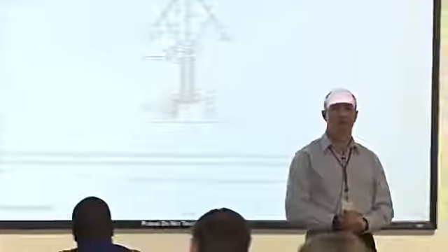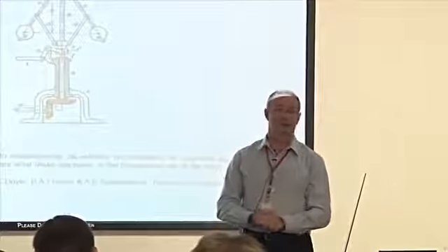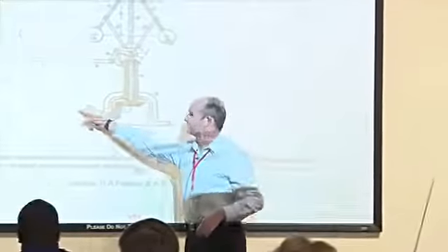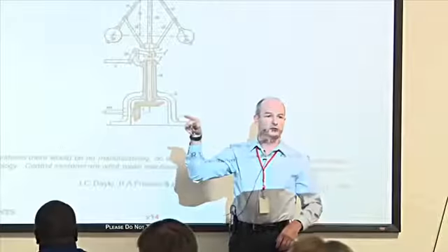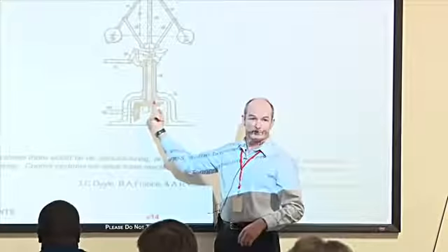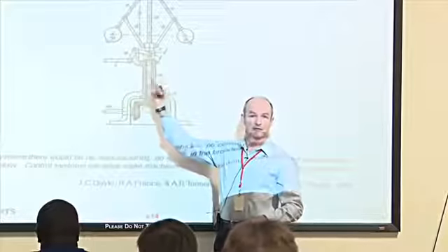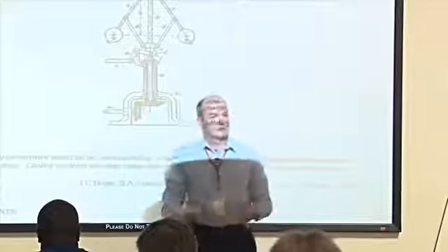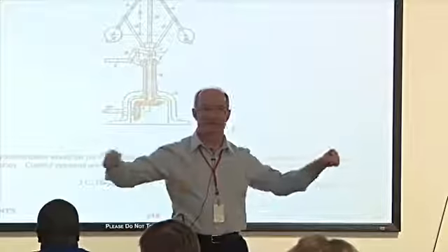It was invented in 1788 by a Scots engineer called James Watt, and its purpose is to regulate the speed of a steam engine. The shaft of the engine enters on the left side through this shaft marked M, and its rotational movement is transferred into the vertical axis by this bevel gear. So as fast as that shaft is spinning, this whole vertical assembly is spinning, and along with it, these two masses. And obviously, the faster the spindle turns, the more the centrifugal force pulls those two masses apart.